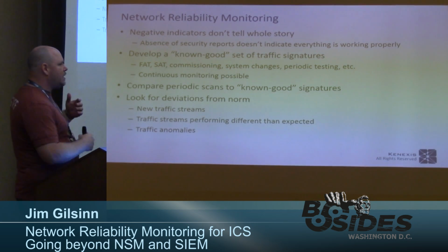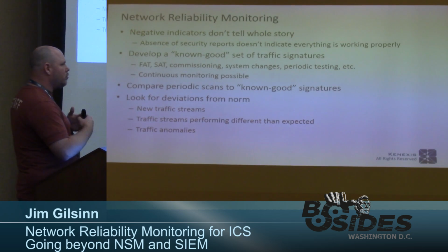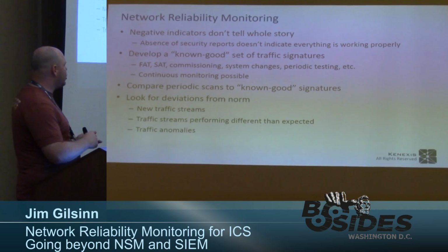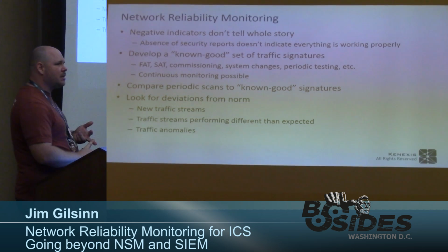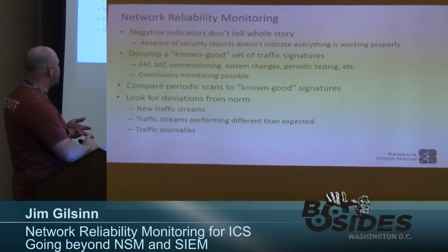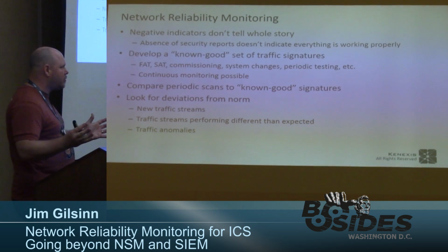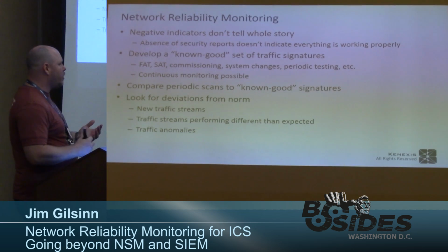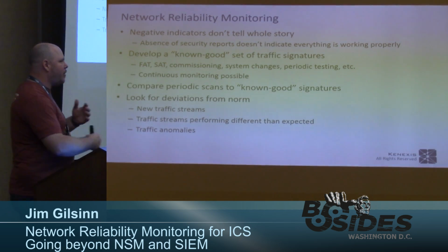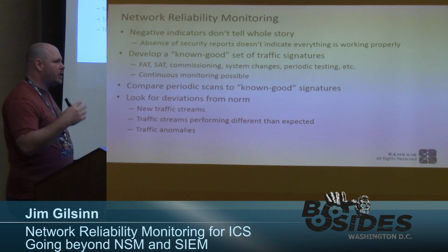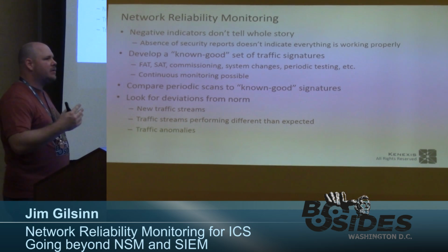And so these systems generally go through multiple levels of testing before they're actually up and running. There's usually some sort of factory acceptance testing of the systems before they even get to the site. Then there's site acceptance testing. Before there's actually startup, a lot of times there's some sort of commissioning testing of the whole system. Then when you have major system changes, a lot of times they will have to go through and recertify it.